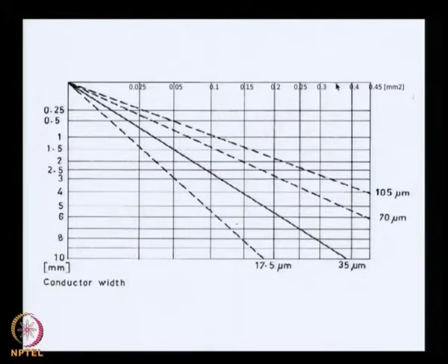So, you would project the cross section area onto that laminate thickness line, and then go to the y intercept, and find out what is the track or the conductor width that is needed for that particular application. This way, you could use these two graphs together to find out what conductor widths to use in the routing rules for a given current.